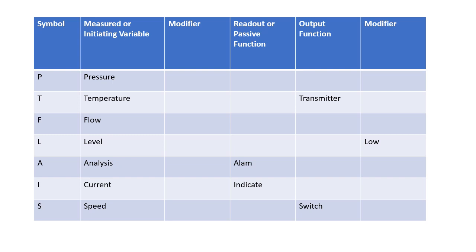In the P&ID, there are multiple symbols you must have noticed, which can be in a circle or in any other form, and you will find some letters written in them. The significance of that letter you can find out from this chart. For example, if it is written as P, it signifies pressure. If it is written T, then it signifies temperature. They signify pressure and temperature when they are at the initial position. But when the T is at the last, it signifies temperature transmitter.